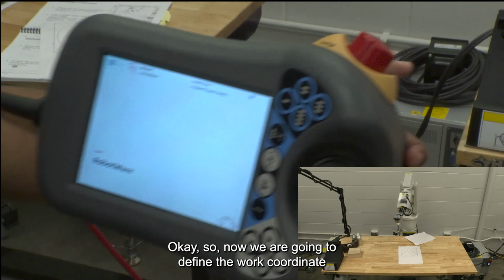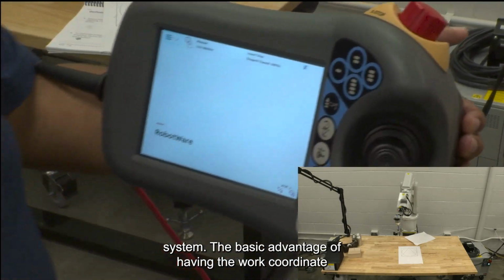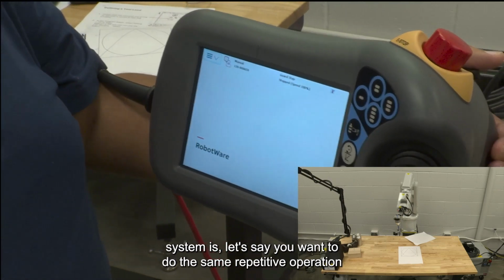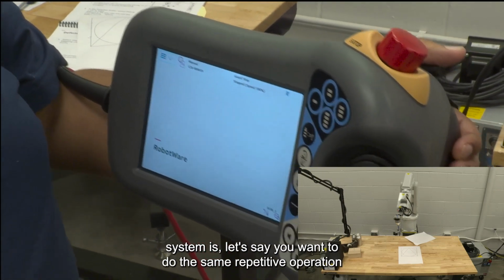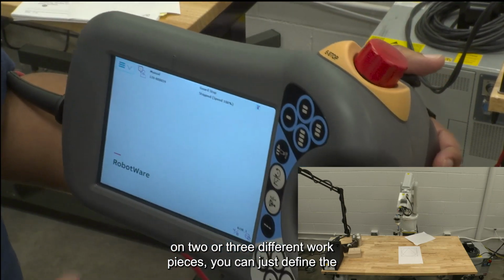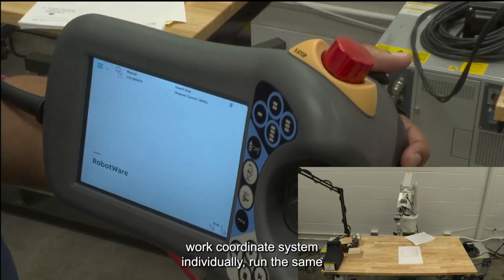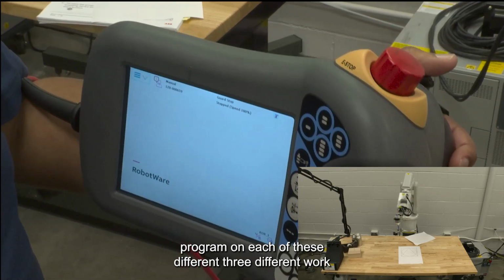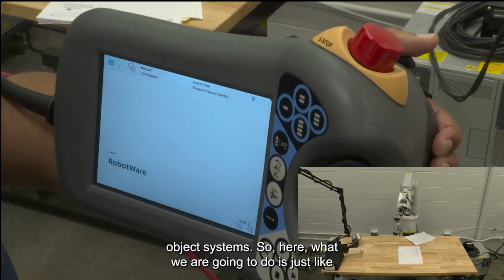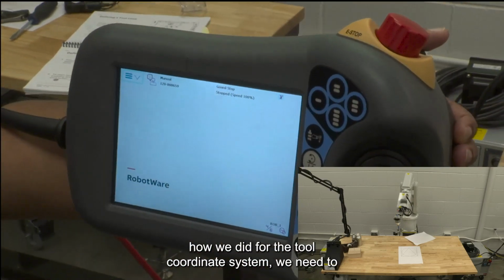Okay, so now we are going to define the work coordinate system. The basic advantage of having the work coordinate system is, let us say you want to do the same repetitive operation on 2 or 3 different work pieces. You can just define the work coordinate systems individually and run the same program on each of these 3 different work object systems.